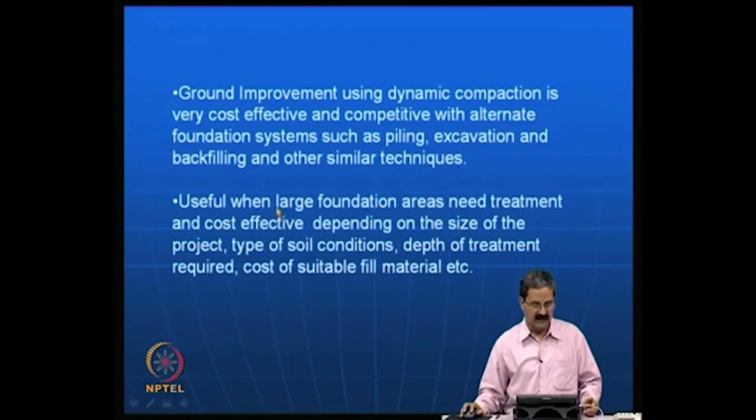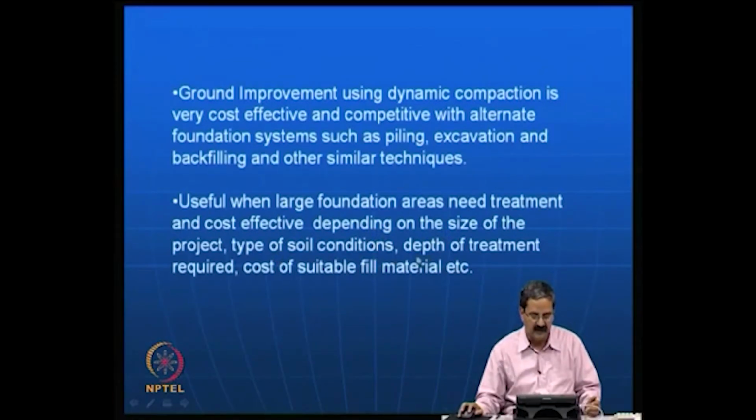So this is particularly very useful when you are trying to handle large foundation areas, for example coastal areas. They result in cost effective solutions, because it depends on the size of the project and the type of soil conditions. As I just mentioned, the techniques of dynamic compaction have quite a big range, from municipal solid waste to sands, it can take care of them.